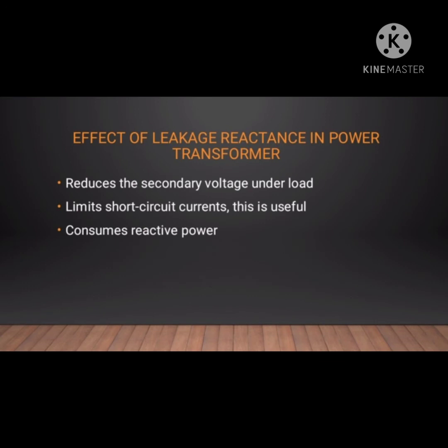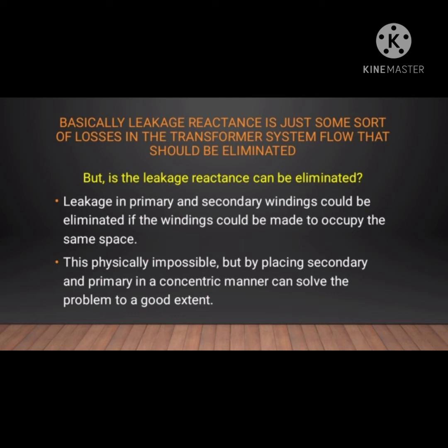So, the effect of leakage reactance in a power transformer. First, it reduces the secondary voltage under load. It limits short circuit currents. This is useful, and it consumes reactive power. So, basically, leakage reactance is just some sort of loss in the transformer system that should be eliminated.